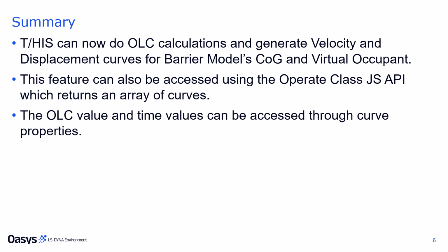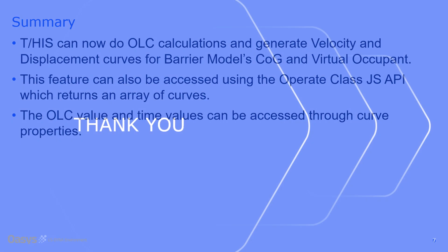THS now supports OLC calculations, generating velocity and displacement curves for the barrier model COG and virtual occupant. This feature is also accessible via the operate class JS API, which returns an array of curves. The OLC value and OLC time can be assessed through curve properties. Thank you.